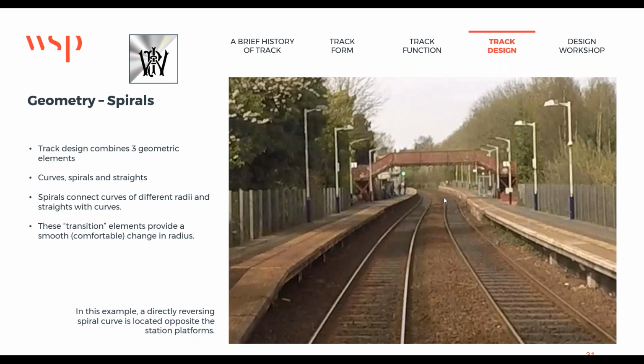And I know as a maintainer, when you come across that kind of thing, if you're going to require treatment to track top, you'll probably require more treatment in this area here, where there was a wider space or an uneven space, than you will in here, where you've got the solid confinement of the platform riser wall, especially on curved track. And that is an influence that's there.